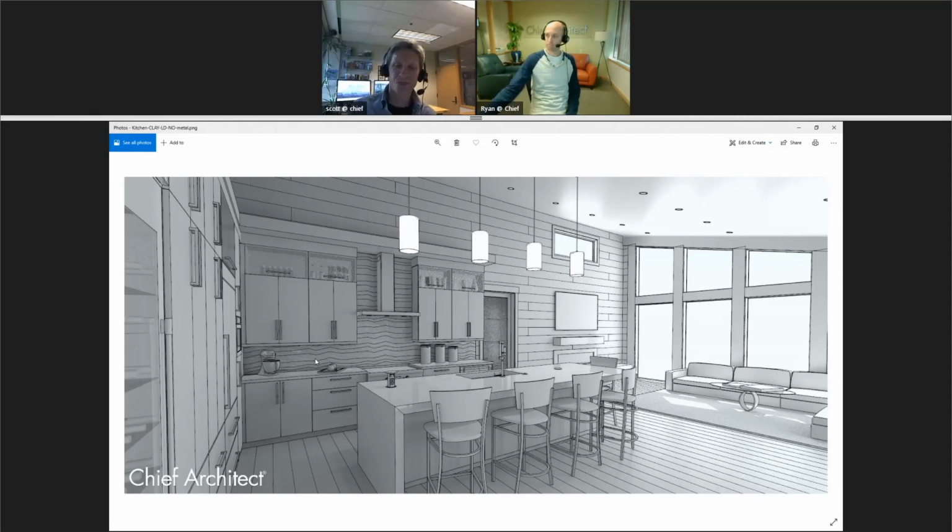Yeah, I've been doing some work in Twinmotion, bringing my models in, and there are a couple of features with materials where you can actually change materials in a 3D view and size things like wood and things like that. One of the other important things, and I'm hoping that we'll be able to do it here, is it has a feature where you can parallel your vertical lines when you're looking at a scene. So like your camera's not tilted, it automatically makes your vertical lines straight up and down to where you get a realistic view versus kind of like tilted to the side. Is that something that we're addressing here?